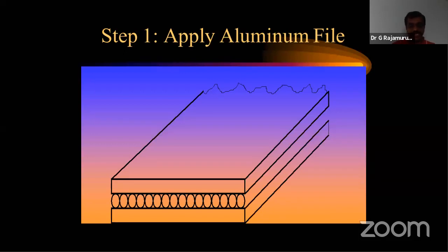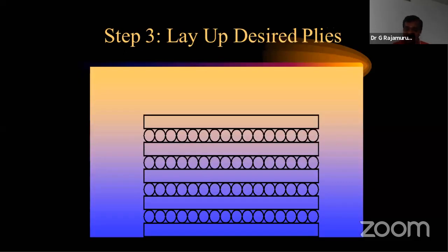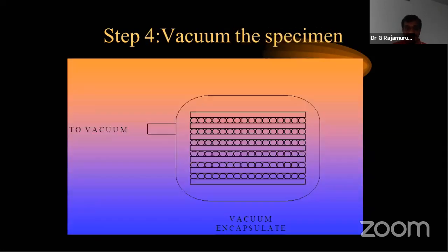So you have to do some perforating holes on the particular aluminum substrate at a constant distance. So then only the matrix will go into that particular hole and give some bonding between the aluminum matrix and the aluminum foil. So, okay, that we'll discuss later. Okay, so these are all the alternate layers of the aluminum and the aluminum foil to enhance the strength of a particular aluminum matrix composite.